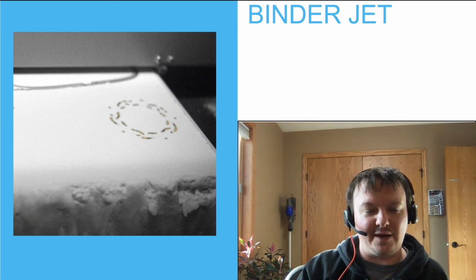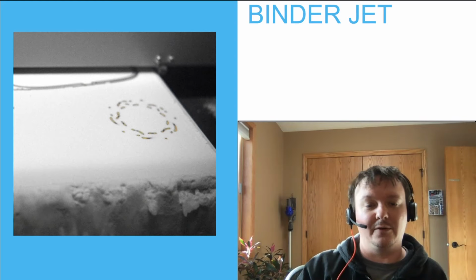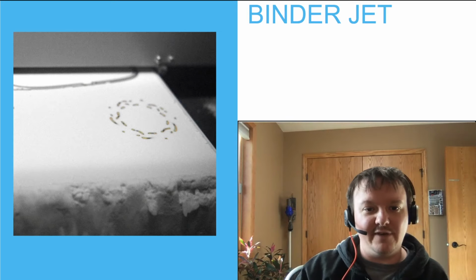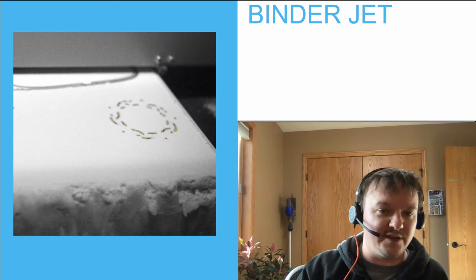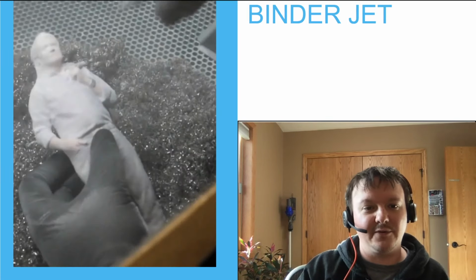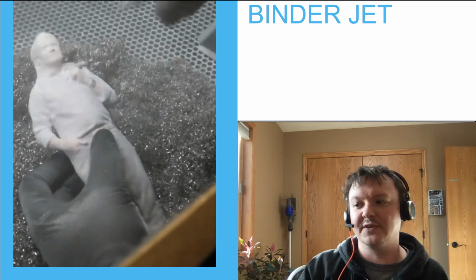The parts that you want to keep, you hit with the inkjet, which solidifies the powder. You keep adding another layer of powder on top, inkjet it all together, and eventually at the end you have a solid object in a bunch of powder. You can remove all the extra powder that didn't stick, and you end up with something like this.